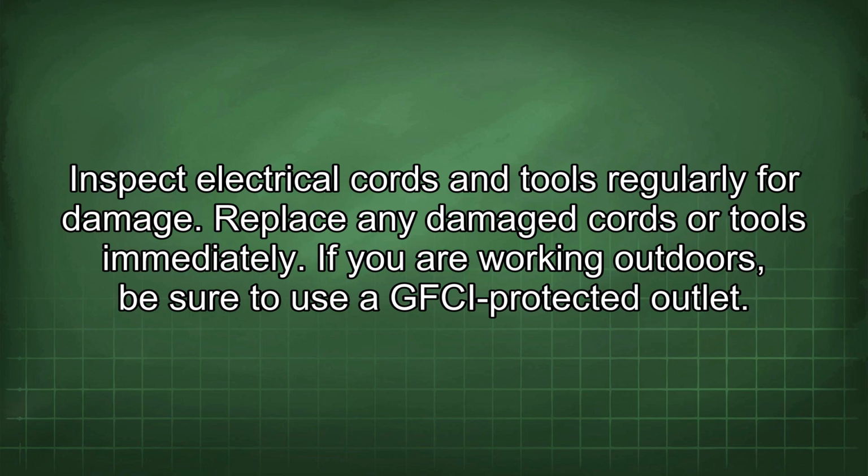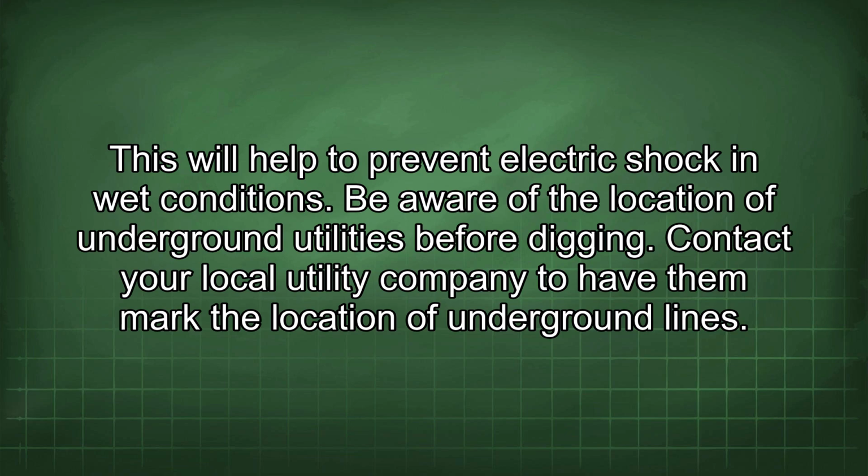Inspect electrical cords and tools regularly for damage. Replace any damaged cords or tools immediately. If you are working outdoors, be sure to use a GFCI protected outlet. This will help to prevent electric shock in wet conditions. Be aware of the location of underground utilities before digging. Contact your local utility company to have them mark the location of underground lines.